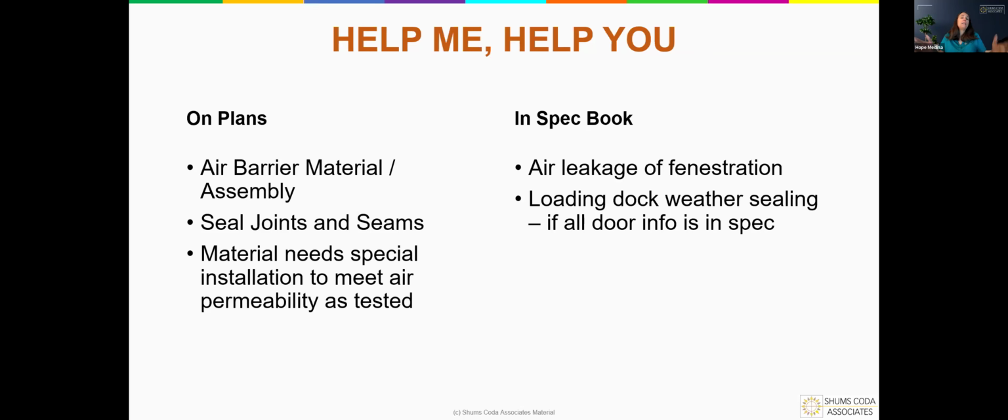And it might not be a bad idea, you should really place all that information in your wall assembly sheet. You put your fire resistant rated construction, your listed assemblies, all of that. So just start including that information, even if it's just a note. The DensGlass is our air barrier. Seal all the joints and seams with mastic. Seal all the penetrations with XYZ sealant. Whatever the case may be, just call it out on your wall sheet. Call it out on your code analysis. And make sure that we have it straight so that we can set up all of our projects to be successful.